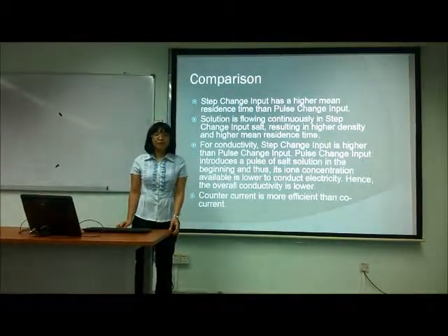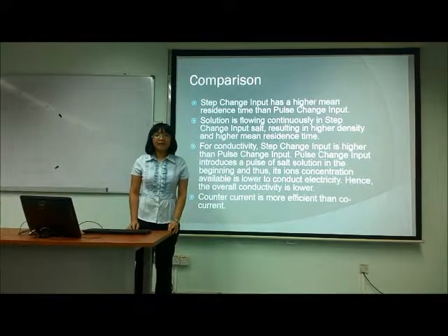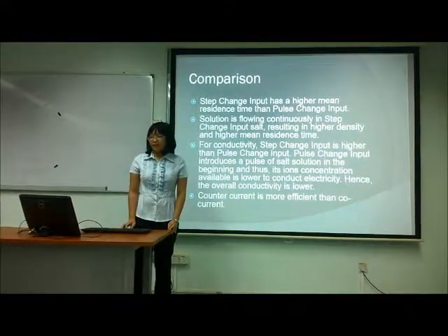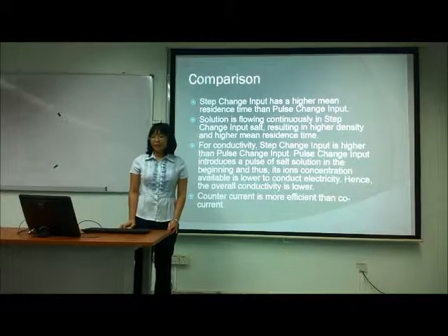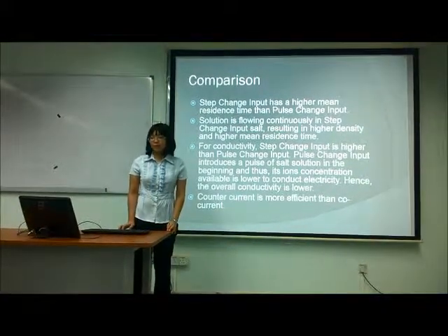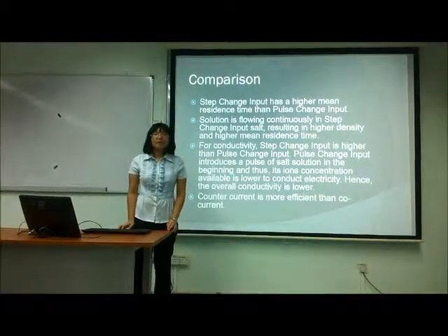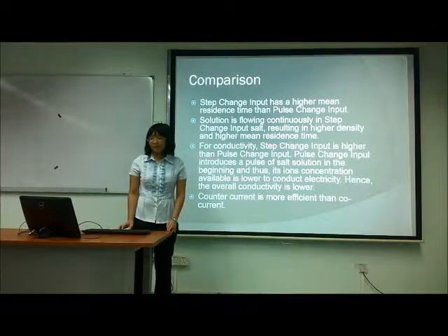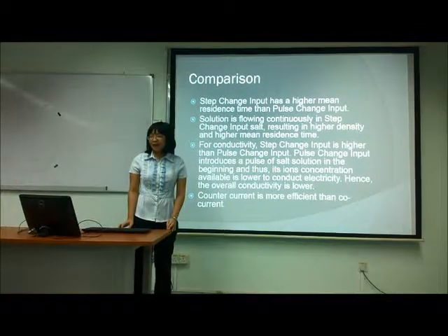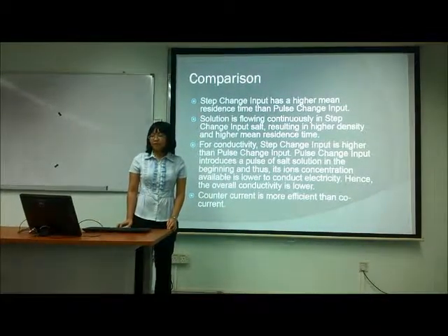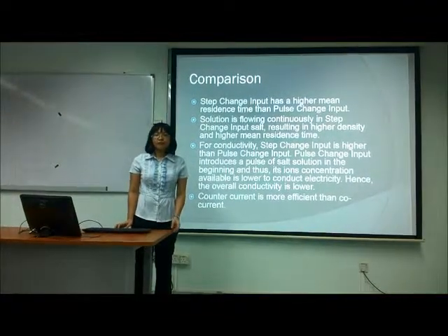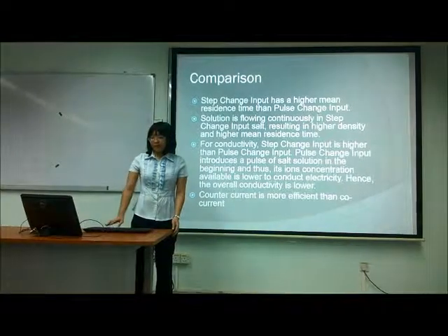So now that we have already talked about experiment part A and part B, we will now do some comparison. We can see that step change input has a higher mean residence time compared to that of pulse change input. This is because in step change input, the flow is flowing continuously into the reactor, resulting in a higher density and a higher mean residence time. But in the pulse change input, there is only a pulse injection of the flow.